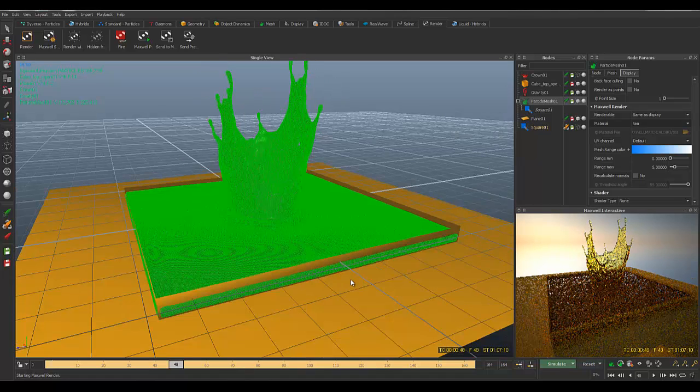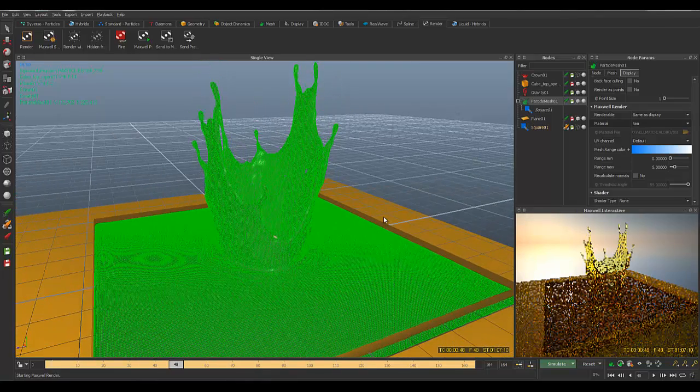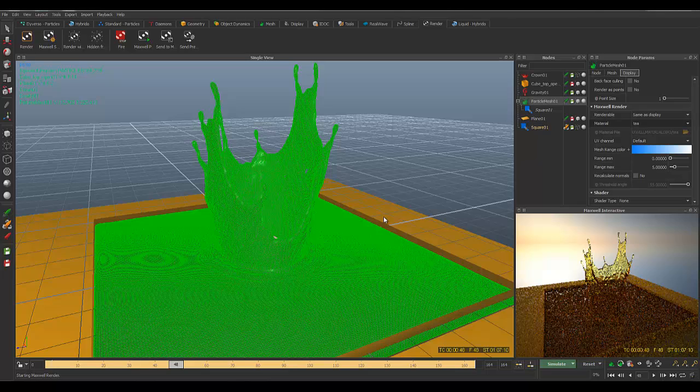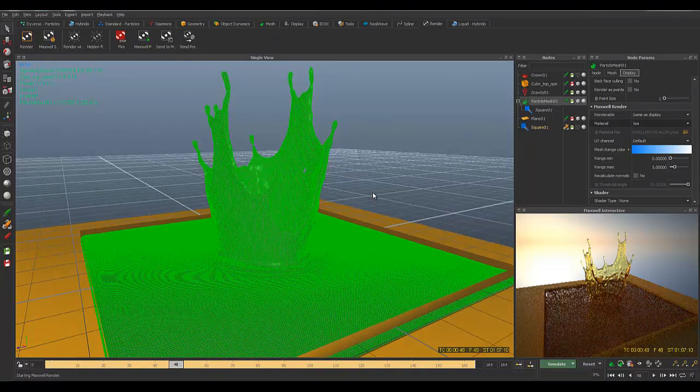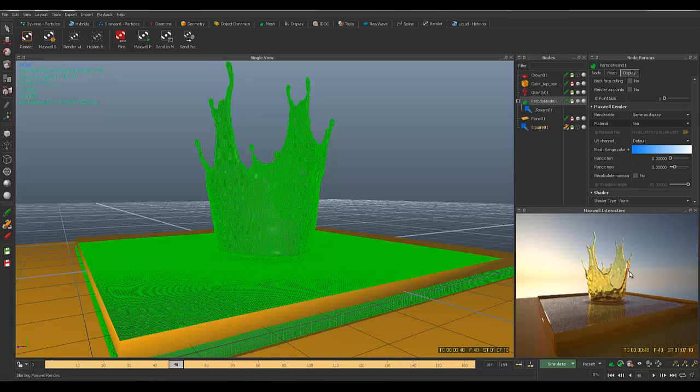and now you can see it's showing me the real-time rendering. And as you can see, my fluid is looking good. As I move my viewport, it's updating in the interactive rendering window. So now you can get the details and get everything I've done in Realflow, and now you know how to create this crown splash effect. Okay, and in 2015 it's really good and fast.